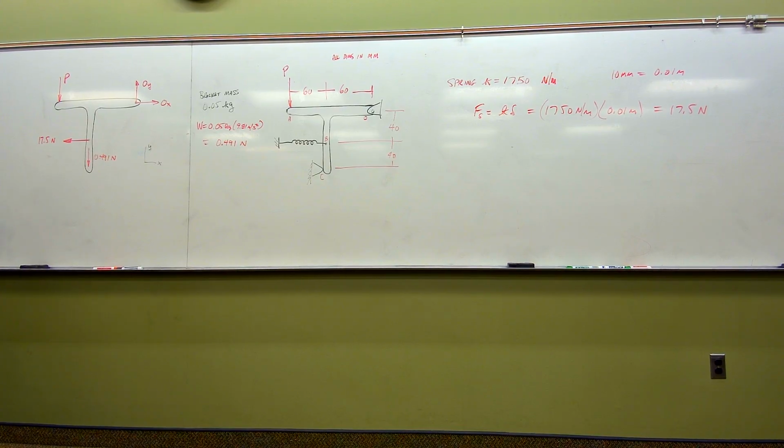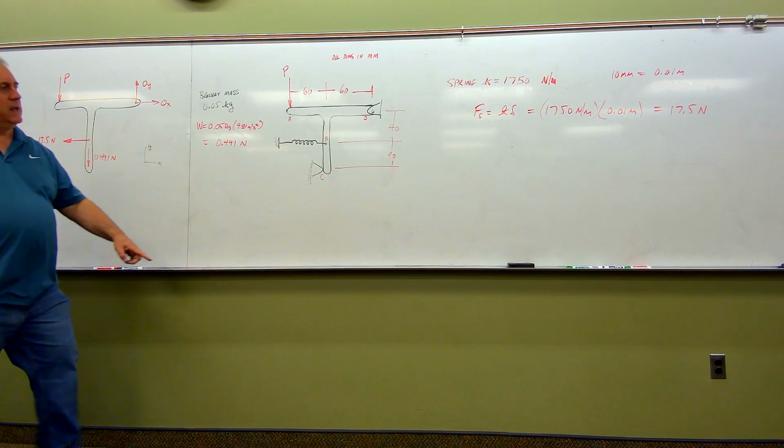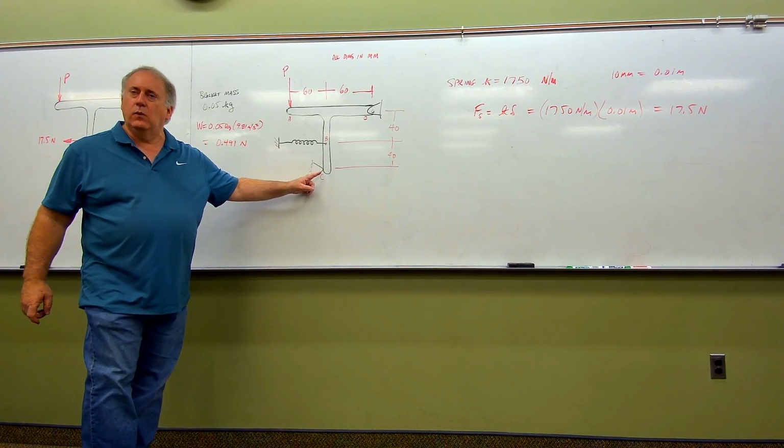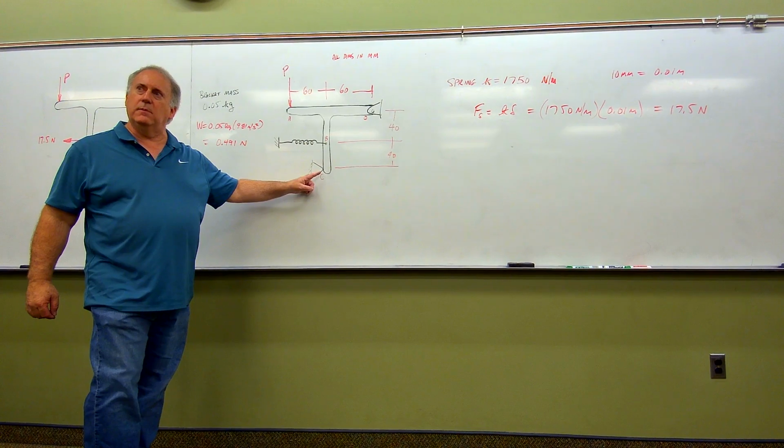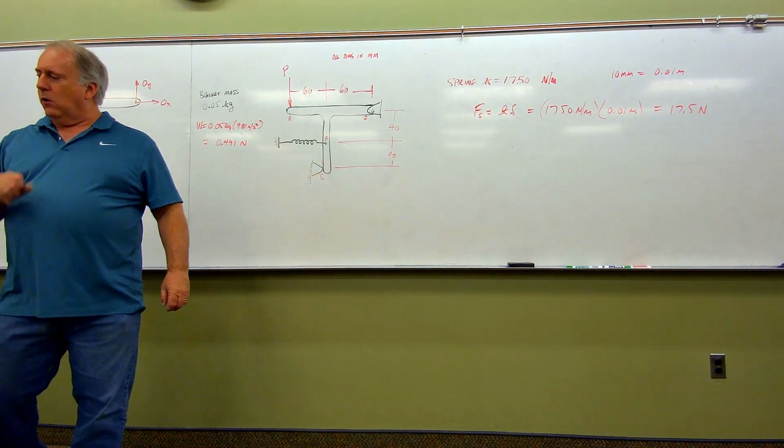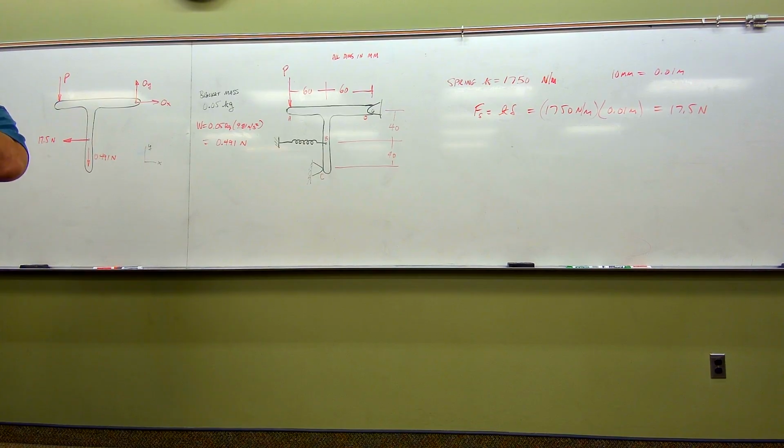On the other hand, it would not have been a surprise at all if your free body diagram would have contemplated that you were in contact here with point C. So since you were in contact, shouldn't there be a force there? Oh, but no. Remember, we saw this just the last time we got together, where every now and then the author's going to slip in some language that tells us that there is no contact. Look at this one here. This one's actually a little bit more overt. It says, determine the force P required to break contact at C. So they were literally telling us we need to know the force it's going to take to let there be no contact there. And if there's no contact, there can't be any force.